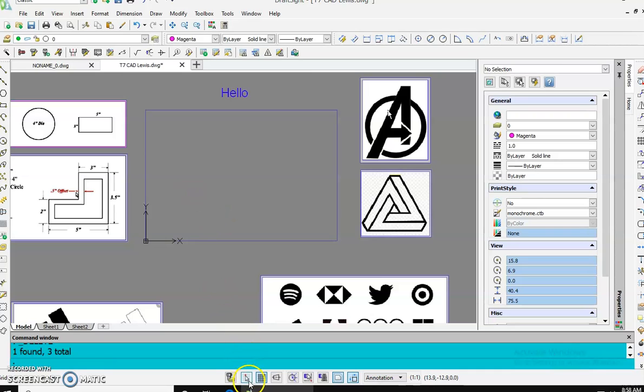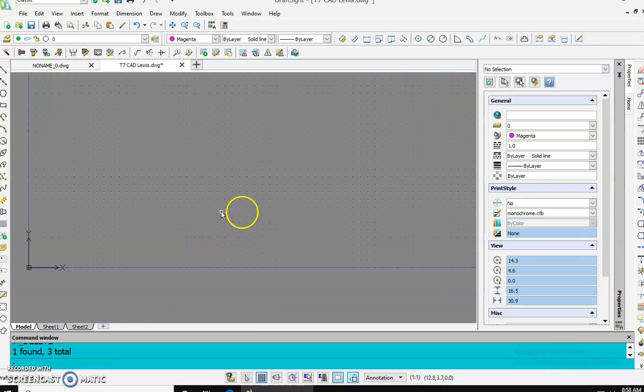Okay. Now, it's a drawing program and it's meant to make very technical drawings. So down here, there are some things that are going to help you out. You have this icon right here. Now, anytime you hover over an icon, it's going to show what it can do. So this is called Snap. This one here is called Grid. So if you like seeing the grid as a visual reference, it's a little light blue color, that means it's on. If you don't like the grid, you can click on it once and turn it off. Me personally, I like having the grid.